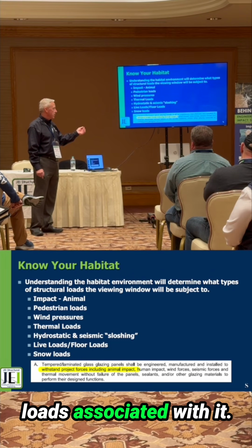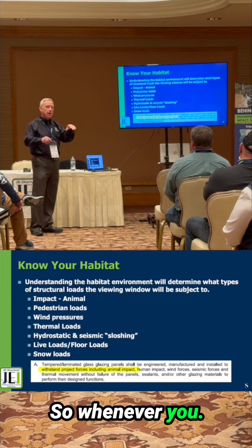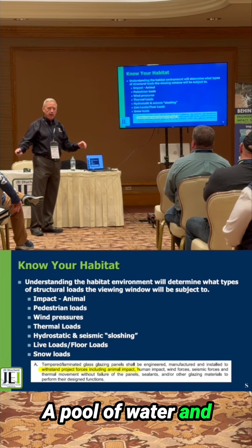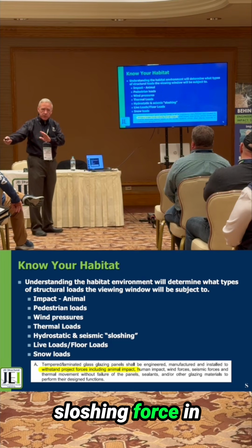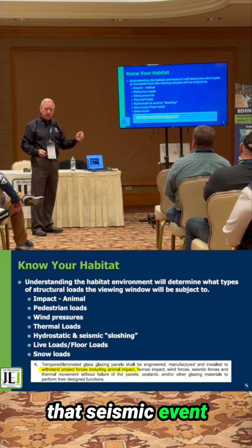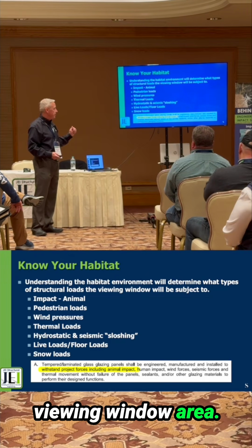Thermal loads associated with hydrostatic and seismic. Sloshing: whenever you have a pool of water and there's a seismic event, there is a known sloshing force in that seismic event that plays a part in designing that glass or viewing window area.